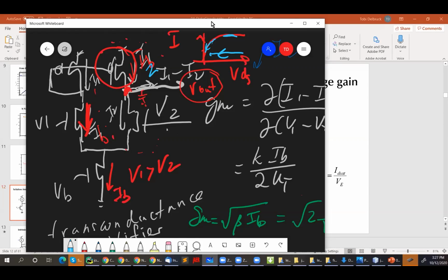Yeah, so if it gets near VDD, doesn't it make the PMOS above triode? You mean it makes the PMOS operate in the triode region, right? And that's true. Close to IB? No, that means the current now will be close to 0. So this mirror is not going to work like a current mirror, actually. So that means I out is not I in, but is actually close to 0. And that's because this transistor is no longer in saturation.